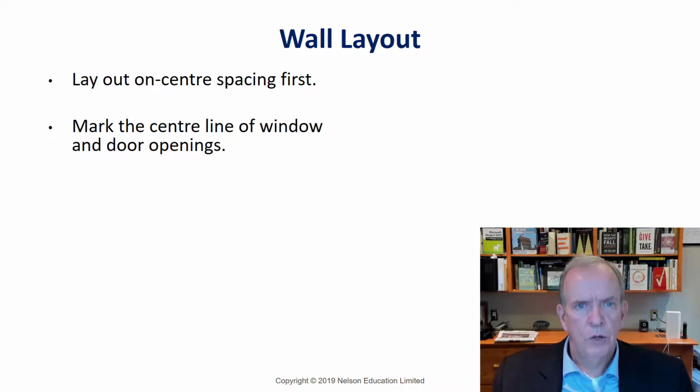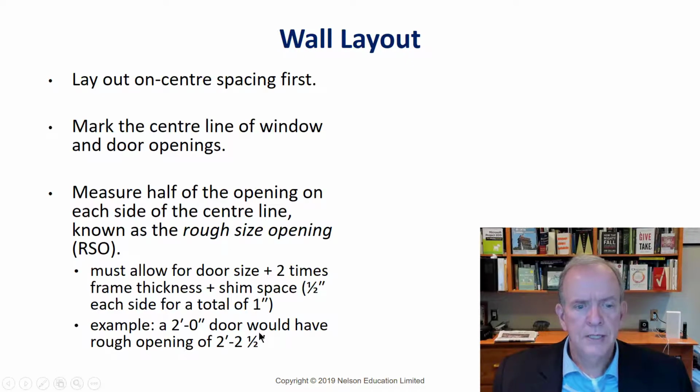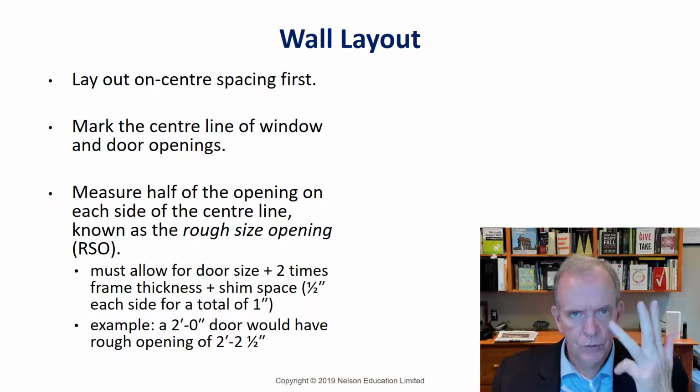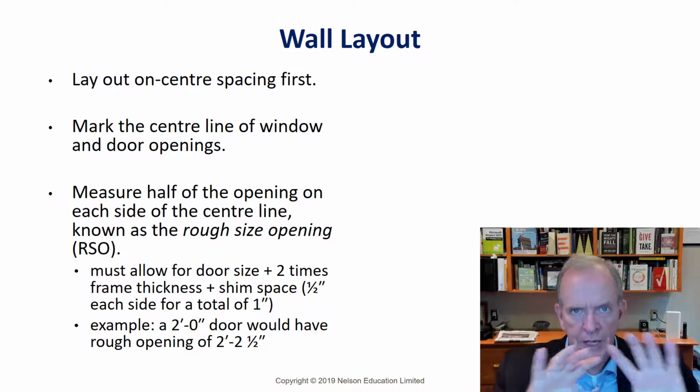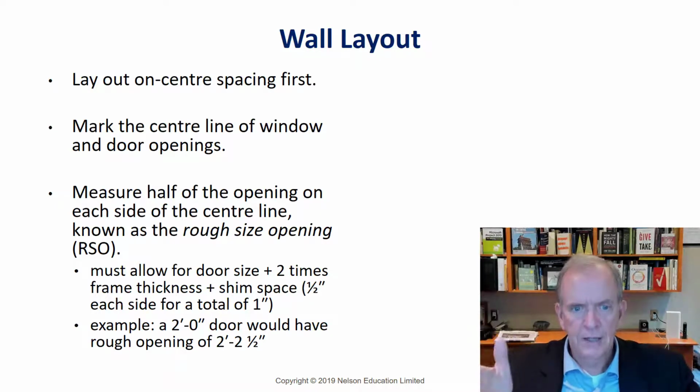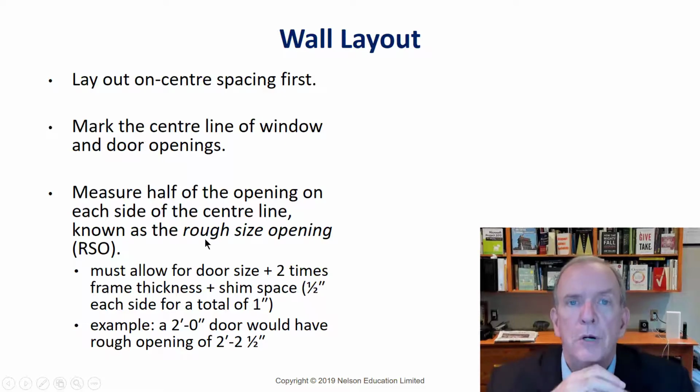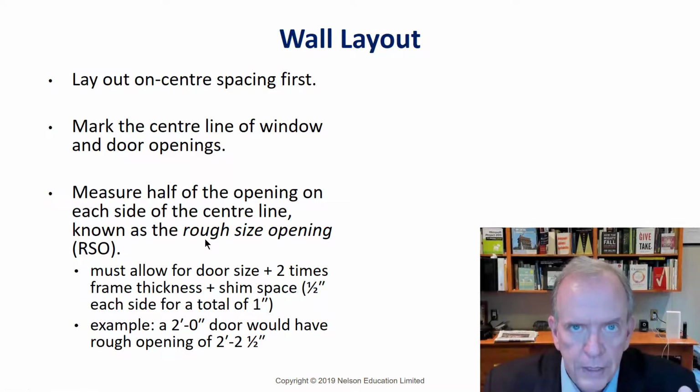Layout. So a wall layout, your spacing, like I mentioned, it's going to be 12 inches, 16 inches, 24 inches, or 19.2 inches. Remember, 19.2 divides evenly into 8 feet, so your sheet goods can join up exactly on a stud. When we do openings, it's very important to know that the openings are going to be larger, right? Larger than whatever you're putting in it. If they're not, you got a big problem.